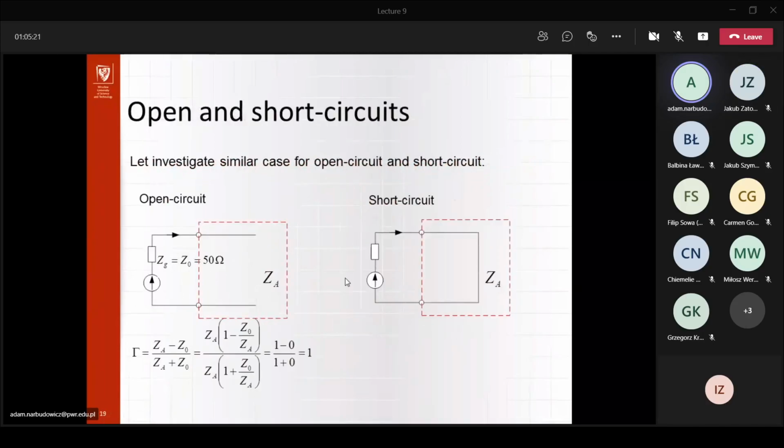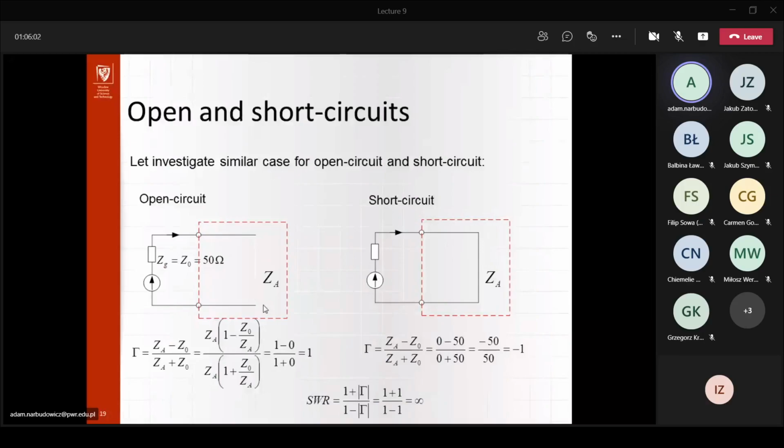Right. So by the way, it's actually just very good exercise if you are trying to figure out a certain equation or certain circuit. It's always good advice to calculate a very simplified case of two extreme cases, and quickly make a quick calculation of how the circuit will behave for that case, just to give you a quick feeling or intuition of what's happening in the circuit, which is exactly what I did here, right? I took the open and short circuit, which are the two extreme cases.